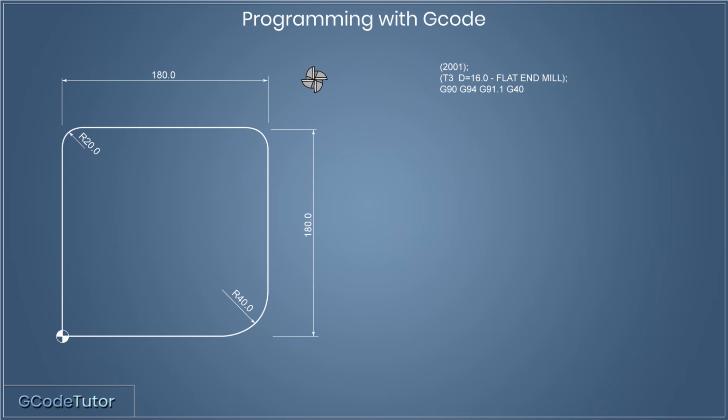So here we have G40. Now this G code cancels any active cutter compensation. When we program, normally we program to the center line of the cutter and tell the machine the diameter of the cutter so it knows how much to offset it by. That way we can program to the actual dimensions of the part and we don't have to allow for the radius of the cutter. Well, G40 just cancels any radiuses that the machine may have in its memory of the cutter. So G40 means cancel cutter compensation.